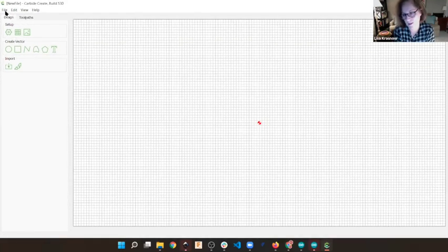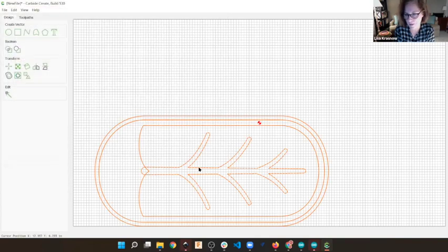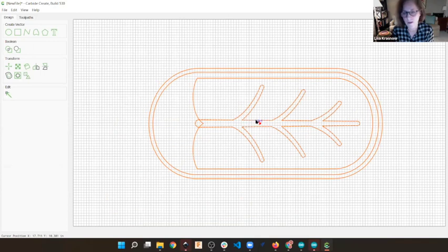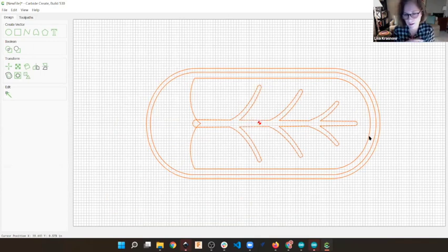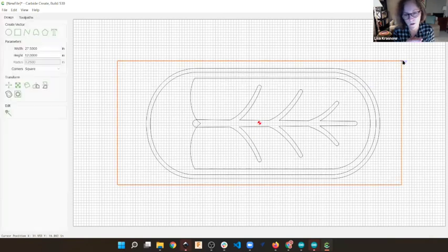We ran it, or we started to run it, and unfortunately we didn't clamp it down hard enough. We thought we did, and it started moving halfway through. Luckily I didn't care, because I could flip the board over and try again. So we clamped it even better by gluing pieces onto the side of the board, butted up against the recesses in the bed of the Shapeoko. Once we thought we really had it firm, we started to run it again. It didn't run fully correctly, because it didn't obey what we thought we told it to do.